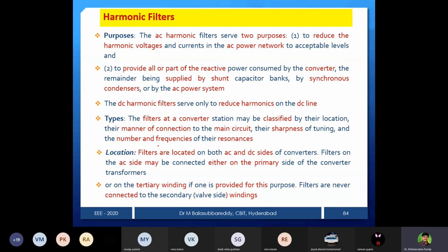As you are aware, in machines also a tertiary winding is used, in substation transformers and all. In substation transformers a primary winding is there, a secondary winding is there. In addition to that, there is a tertiary winding, also called the third winding. The rating of the tertiary winding is less than the primary and secondary. This tertiary winding you connect to auxiliary components. Suppose a substation is there, we are giving input to the station and taking the secondary, transmitting to the lines.